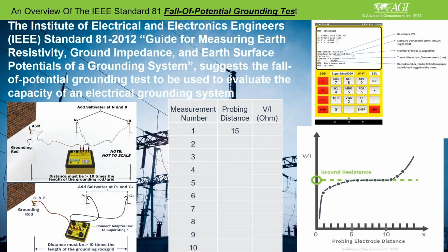So if that grounding grid is located in the wrong place, or the grounding grid was already installed but many years have passed, you need to check this from time to time, which is very important, because the resistivity of the ground changes depending on rain season or dry season, the compactness, and many other influences in the area. So if the ground becomes more resistive, then you may get trouble.